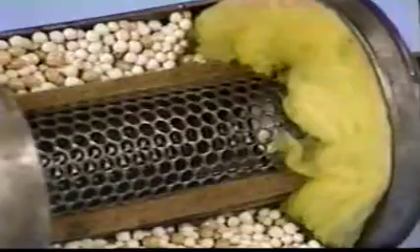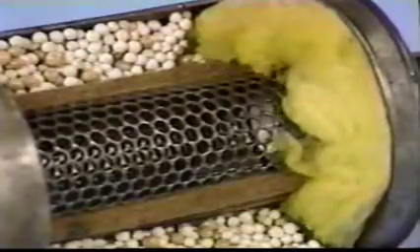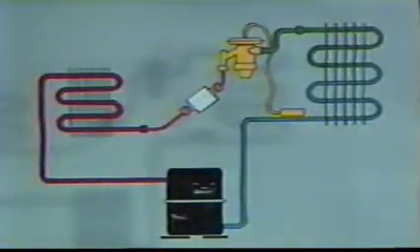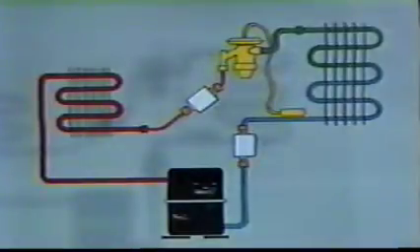Because of its high capability to remove suspended contaminants as well as acid, the installation of a suction line dryer is an absolute must after a compressor burnout. A strong case can also be made for installing a suction line dryer in any system where long-term reliability is a requirement. While it's true that the liquid line filter dryer will rid the system of most soluble and suspended contamination, the suction line filter dryer is an inexpensive insurance policy against compressor failure due to contamination.